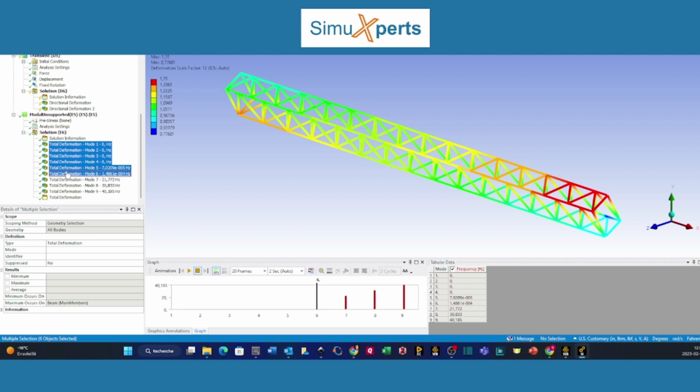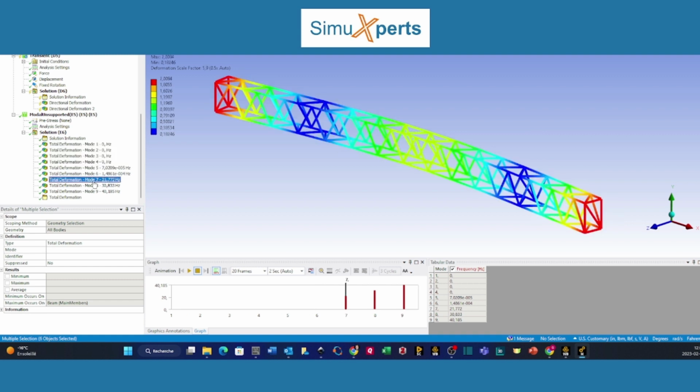But what really matters is that the highest of these 6 frequencies, which happens to be 1.461 10 to the minus 4 hertz, is very, very small compared to the seventh mode, which is at 21.7. So you want a big gap; you want the ratio of your largest rigid body mode to the first flexible mode to be very small.